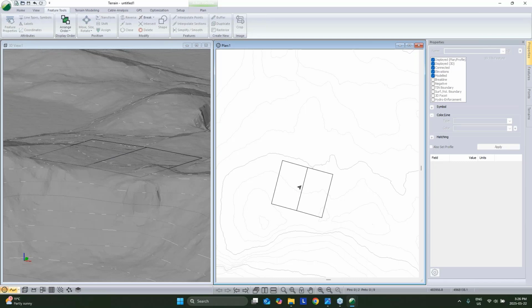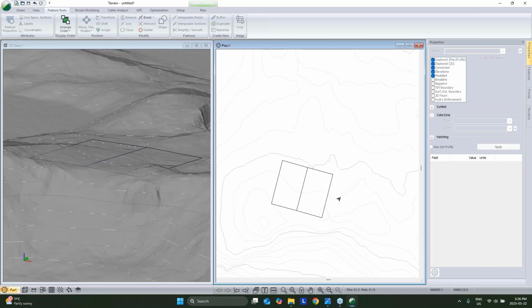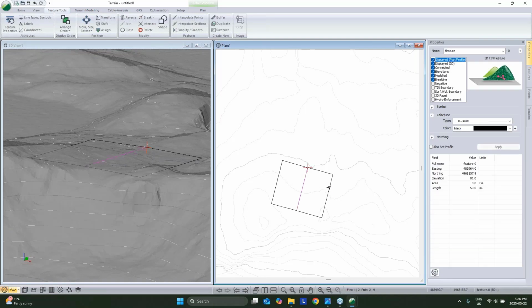And for this, if I want to auto grade this, and if I want to move my crown up and down simultaneously with the boundary feature that I'm grading from, I'm going to have both of these selected. So one selected, two selected, and the feature that's being graded is my current feature. So my current feature is the one that the little red cross is showing up on, so the last one that gets selected in the process.